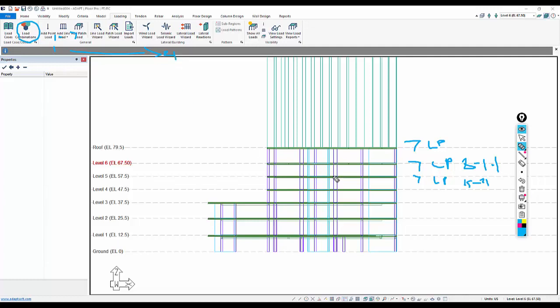If we were running this model globally and we wanted to include the loads for each pattern, we would need to write, maybe we would have one combination service total, for example. And for that service total pattern, we want to determine the stresses based on a global solution, a multi-level solution. We want to determine the stresses for the design strips at each one of these levels based on a multi-level solution.